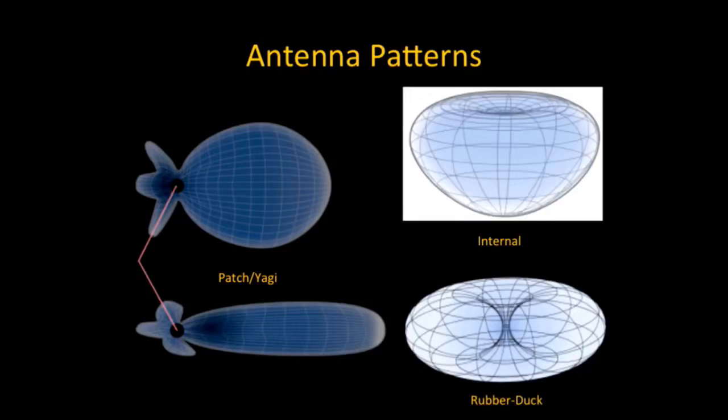And one common mistake we find is when people take a rubber duck antenna. That's one of those single antennas, has a 90-degree bendable arm, and say, I'll just get a higher gain antenna, and it'll increase the size of my donut-shaped pattern. What it does at higher gain, you're not creating energy. If you imagine the energy coming out to be fixed, like the volume of a balloon, you can just change the shape of that pattern. So if I get a higher gain rubber duck antenna, basically what happens is I flatten my donut, so it looks more like a pancake. So I lose vertically, but I might be pushing that energy out further horizontally, okay?